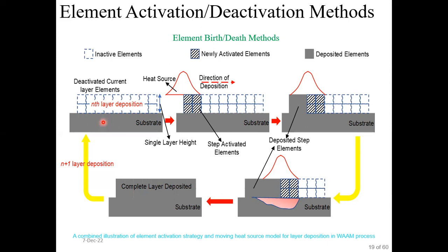However, in FEM practice, it is not possible to add elements with respect to time in a particular solver. So what we have to do is geometrically model all the elements representing the deposition zone at the beginning of the modeling. Before the beginning of the solving procedure, we deactivate those elements representing the deposition zone by issuing the EKILL command. After that, in the second picture, we can see that as the heat source approaches the first instant of this hashed section of elements, which is going to be deposited,